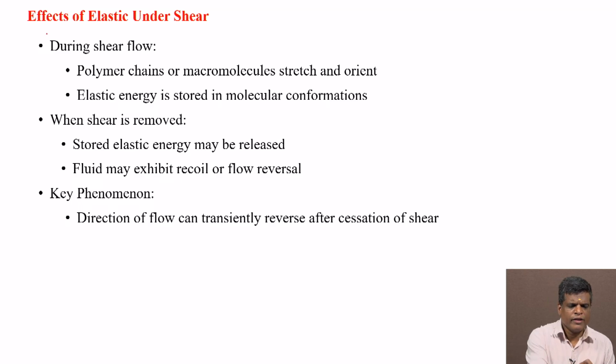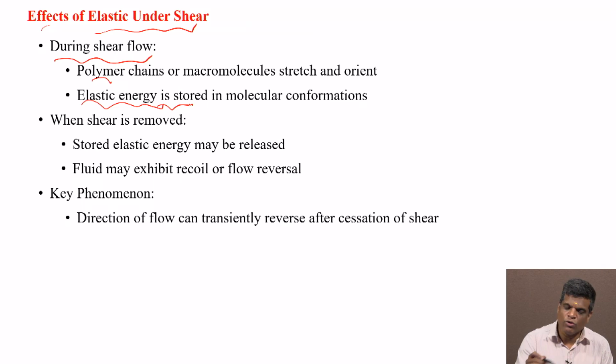So, what are the effects of elasticity under shear? When you apply shear, what will happen? When you release the shear, what is happening? During shear flow, elastic energy is stored in the molecular conformation, in the same way for polymer chains or macromolecules, through stretch and orientation.